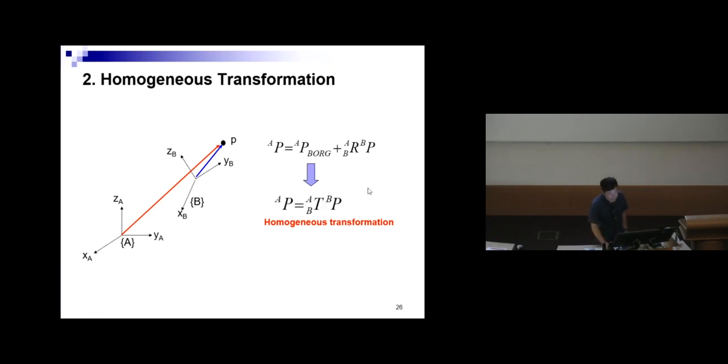So what is the advantage of having homogeneous transformations? It allows the writing to be simpler and the analytical analysis of the transformation a lot easier. But when you actually implement it on your computer, you may not want to do that, especially if you know that there's actually a multiply by 0. So it's for theoretical analysis, more than actual implementation.